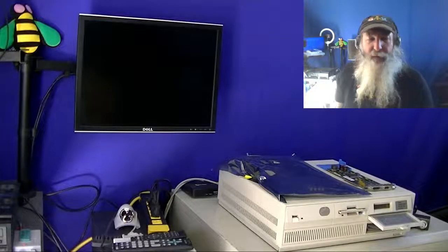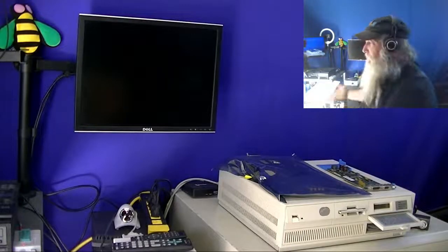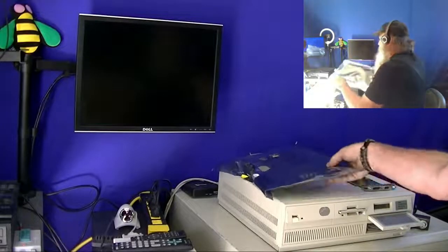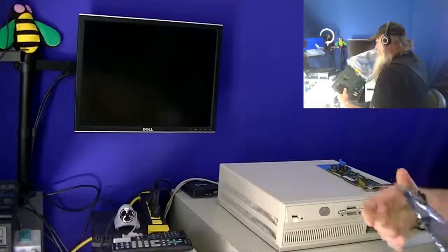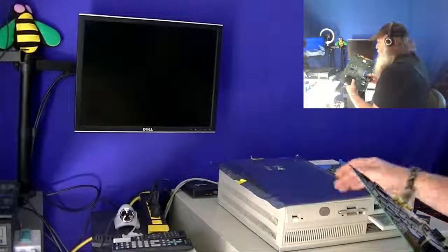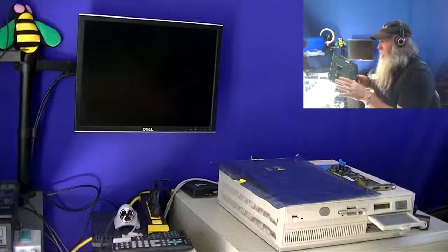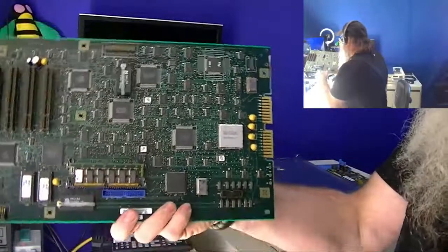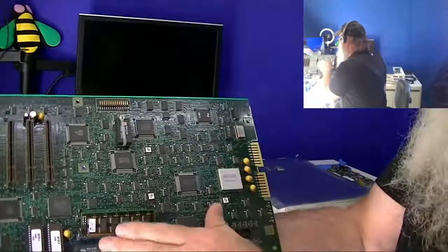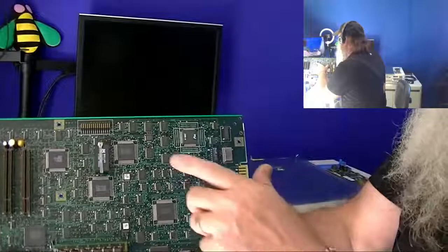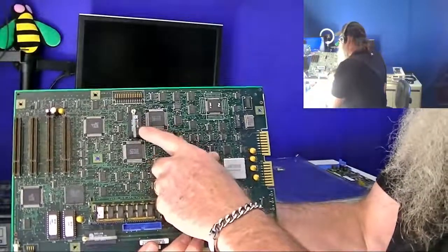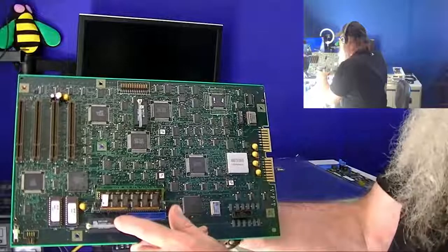But this stream, I'm not going to go to the point of, of course, I haven't powered this up before. There's likely going to be some replacement parts I'll have to look at getting. If these non-volatile RAM modules are sketchy, the DS1287 module is going to be easy enough to replace straight off. I'll have to get more of these on order.